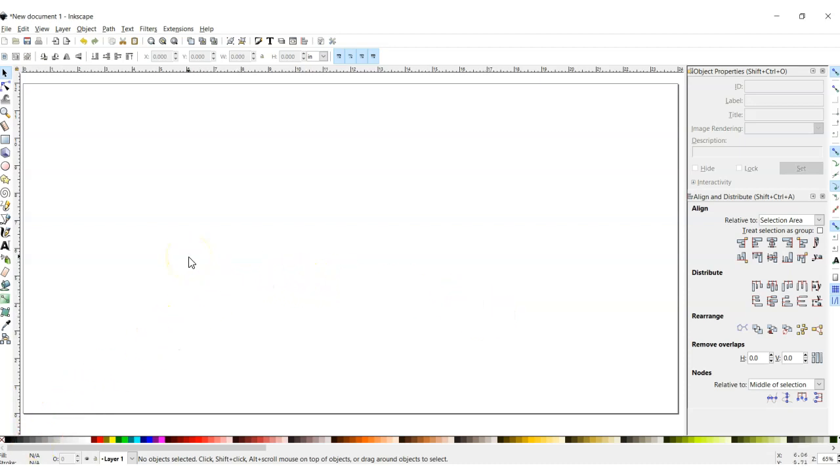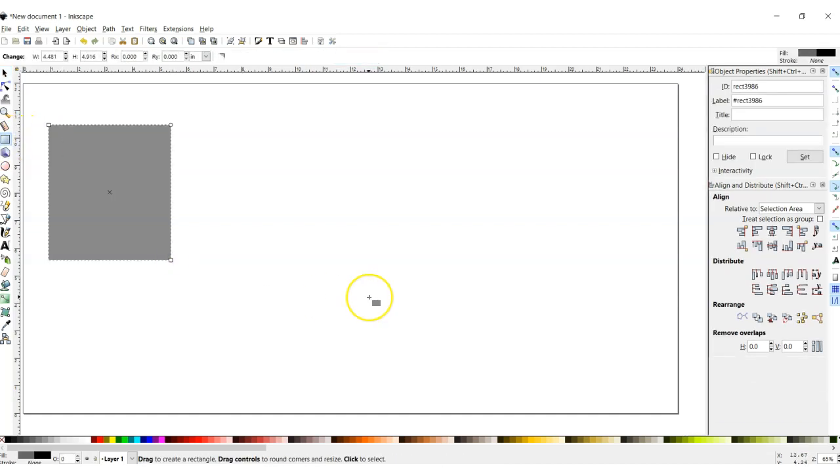So if you think about a basic house shape, you know that it's going to have four sides to it. In Inkscape, we can easily draw rectangles using the rectangle creation tool. Now, your tool might be set up strangely, so let's just do a check here. So click on the rectangle tool and then click and drag. So mine happened to be gray and there's no outline on it. That's fine. Let's make it what it should be at the end.